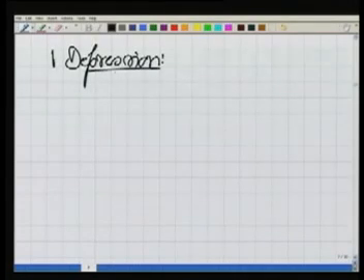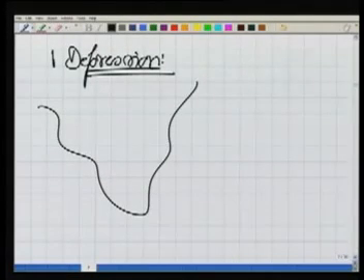What is the meaning of depression? The depression means any feature which is of this shape, the cup shape. Now for this cup shape, if I slice it by horizontal planes, how the contours will form? So there is a depression here. I'm drawing it in 2 dimensions. Of course, it's a 3-dimensional thing there in the field.